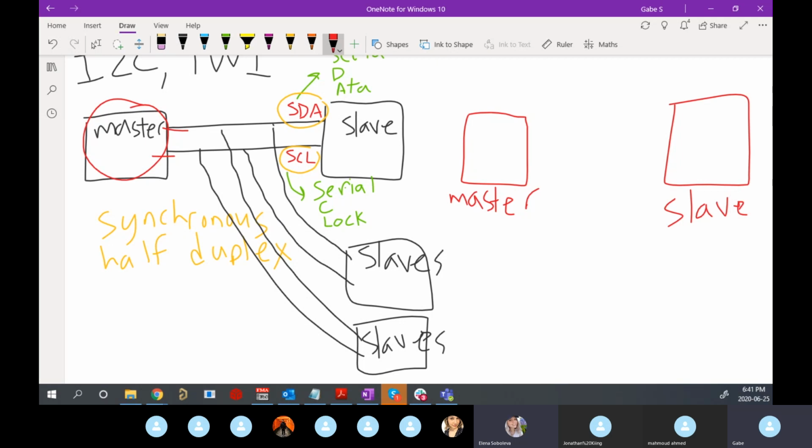Yeah, good question. So a lot of the time, especially with I2C and a few of the other protocols we're going to talk about later, in these languages you sort of need someone to direct the communication. So we usually refer to the person who's controlling the communication as the master. And oftentimes that's whatever microcontroller you're using. You are the master because you're initiating the communication and you're getting data. And a slave could be a little integrated circuit, a little chip you're talking to.